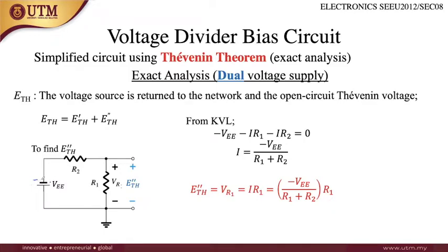So it comes from the minus polarity. So this is positive, this is minus. Current entering the resistor should be positive, coming out minus. So we are choosing this loop. But if you are choosing the other way around, this part should be positive.